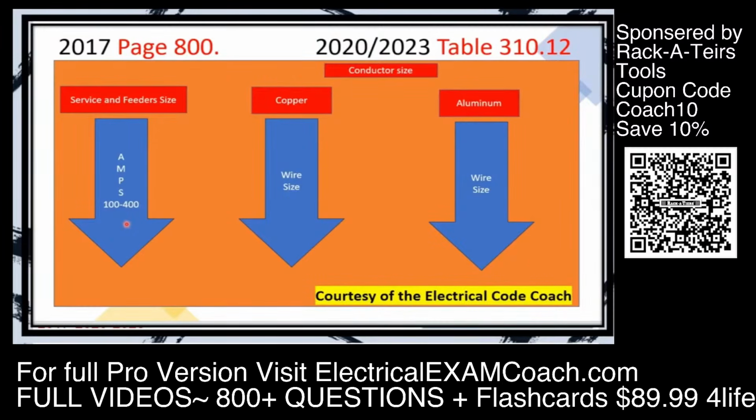And I've got a great graphic illustration in the next slide to show you when it does and does not apply. On the next column over, we're going to see the copper side if we decide to use copper, and then aluminum if you decide to use aluminum. So what you do is size your service. You come down here. Let's imagine it's a 100 amp service and you want to use copper. You slide over and it tells you what size wire to use. It makes it super simple. Now let's put it to practice.